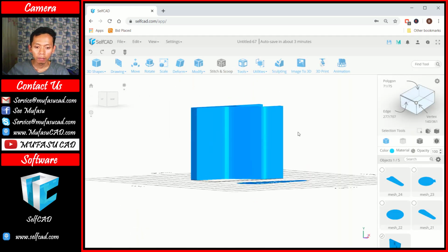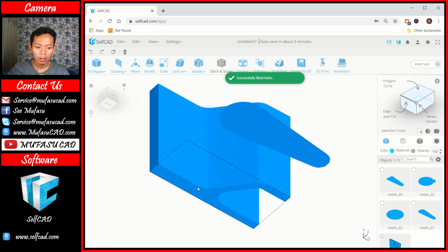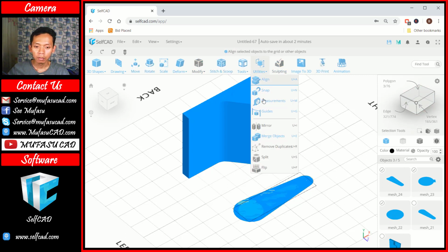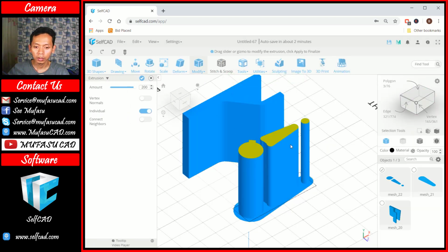Okay, we use fill polygon again to convert this hole. Okay, click tools and fill polygon. So it will be fill the holes in here. Next, I will convert again. Okay, you can combine these objects 1, 2, and then 3. We can use merge objects. Now we can use extrusion again to extrude these models.